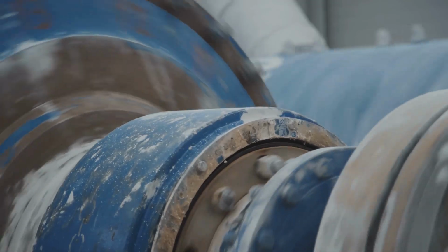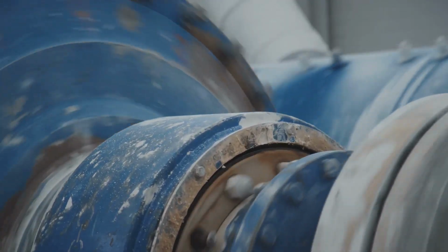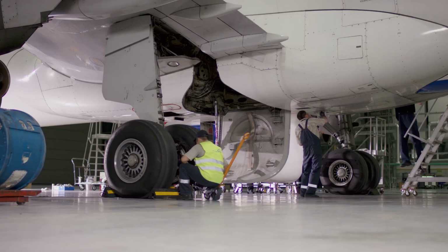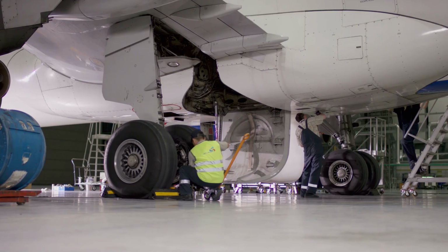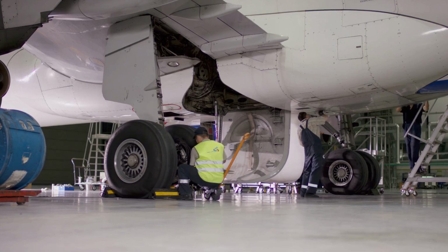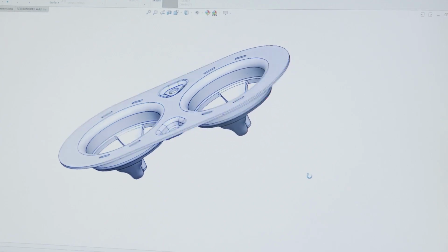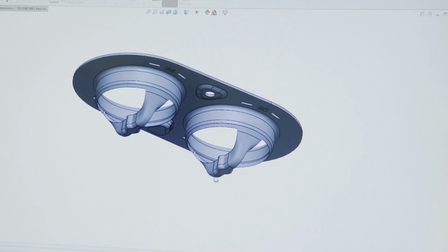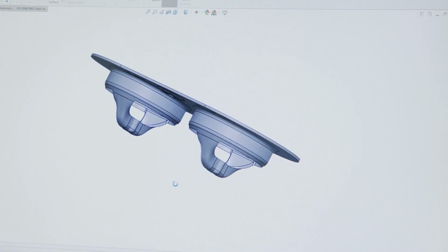It doesn't just look at the force applied, it looks at how the material responds to that force. This is especially important for low-cycle fatigue. This is where a component might fail after a relatively small number of quite large strain cycles, often involving significant plastic deformation. Think about the landing gear of an aircraft. It experiences high loads, but not millions of times a day. The strain life approach captures this behavior with remarkable accuracy by considering both the elastic and plastic components of strain from the very start.